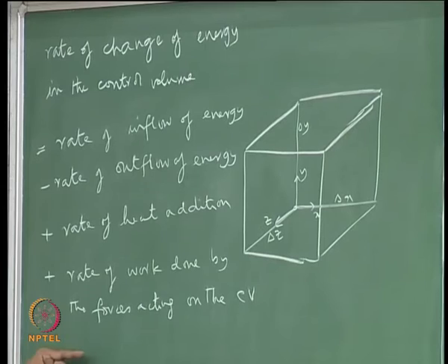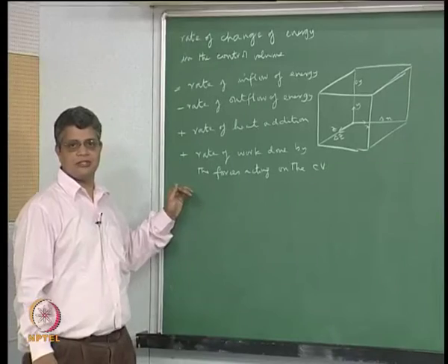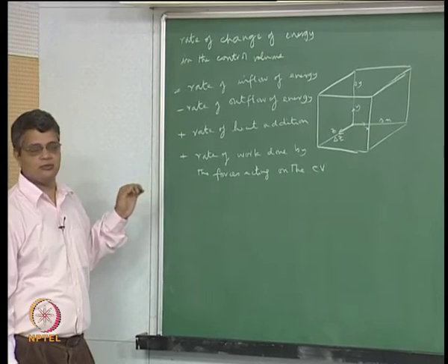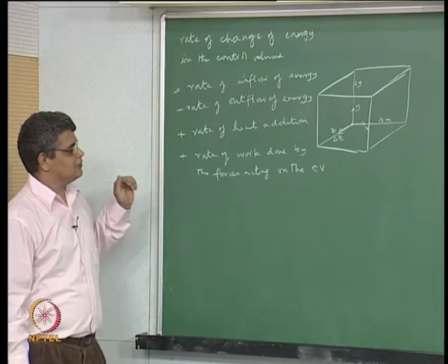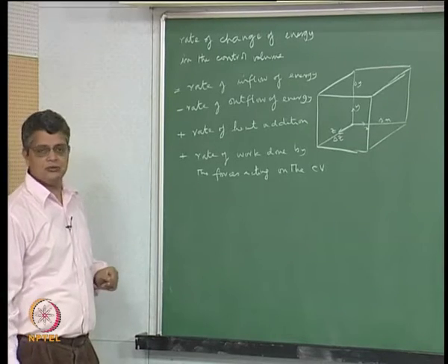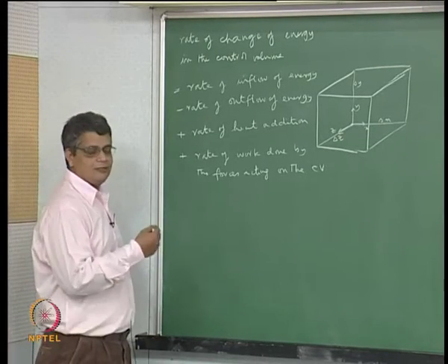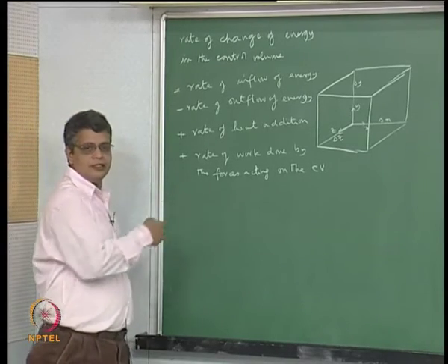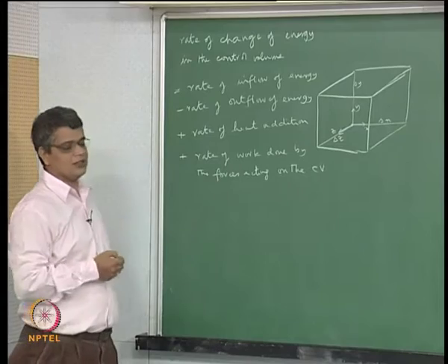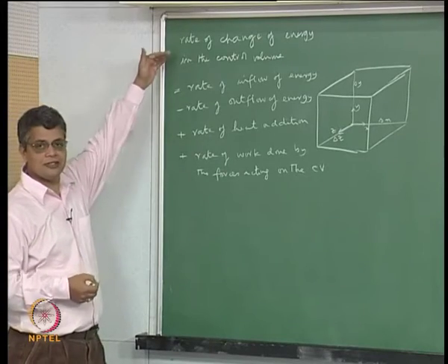These are external forces, and we have made the point that there are stresses, viscous stresses, and also the pressure forces which may be acting, and when you have a force acting on a particular control volume then it can do work and that becomes part of the external work, and if there is external work done on the fluid within the control volume, then its energy content increases.